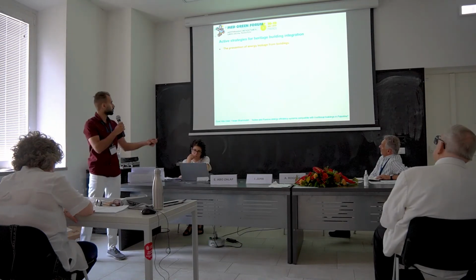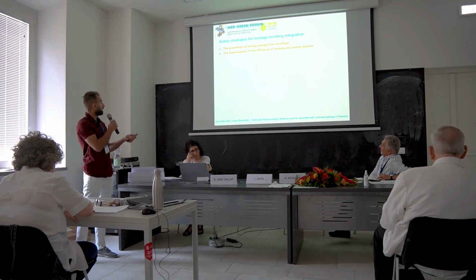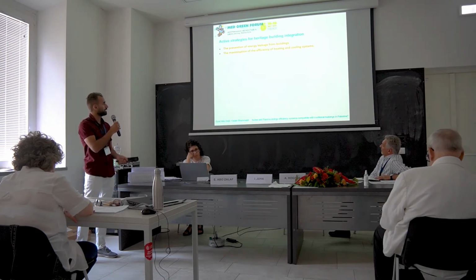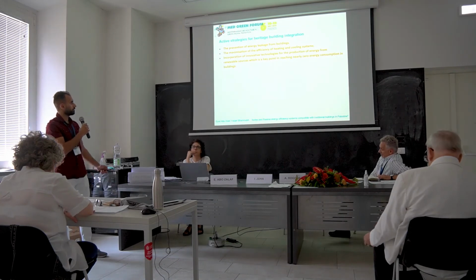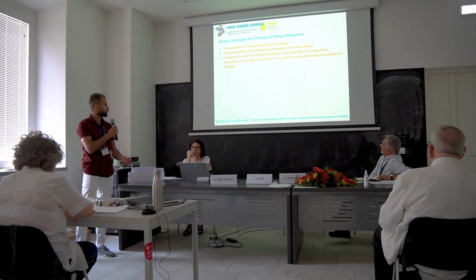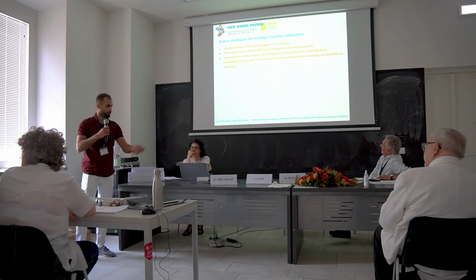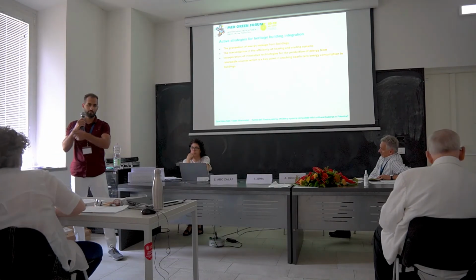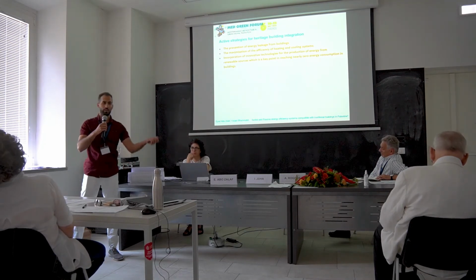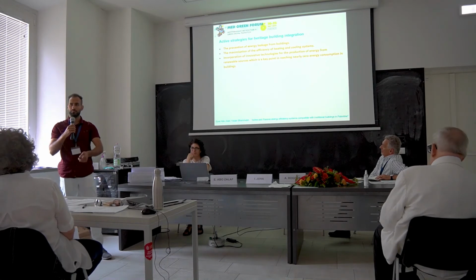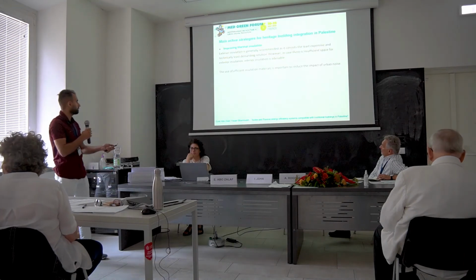When you design, you should aim to prevent energy leakage from buildings, maximize the efficiency of heating and cooling systems, and incorporate innovative technologies for the production of energy from renewable energy sources, which is a key point in reaching nearly zero energy consumption in buildings. I want to say that energy efficiency improvements could save you 25% or more of the building consumption. However, with renewable energy systems, you could cover the rest, the 75%, to reach a nearly zero energy building.